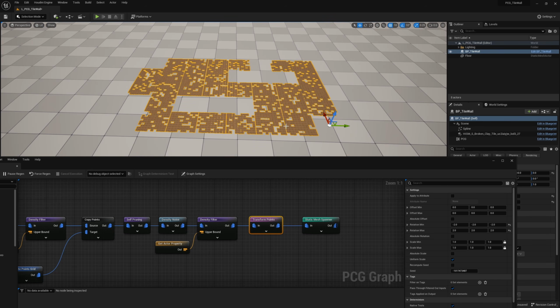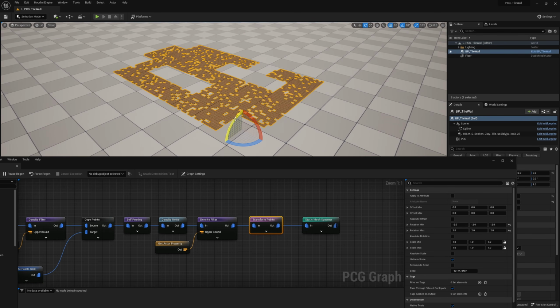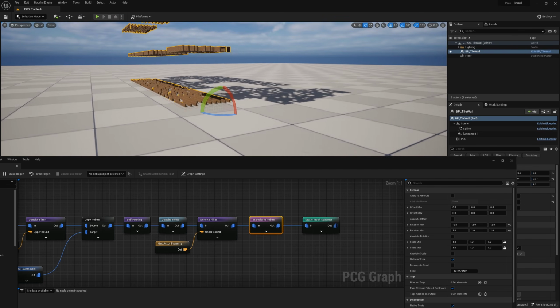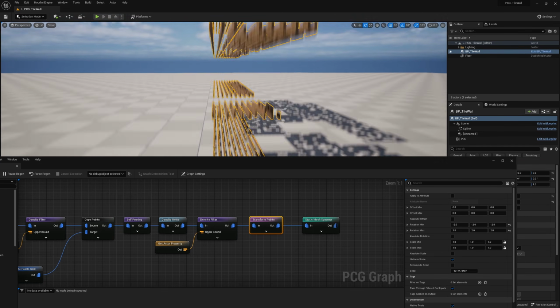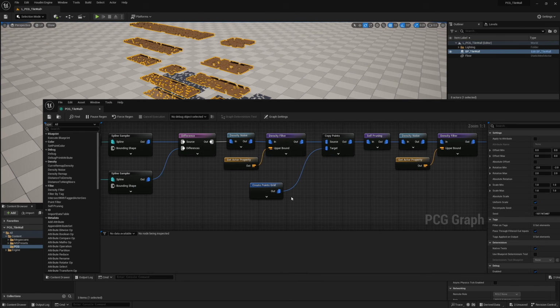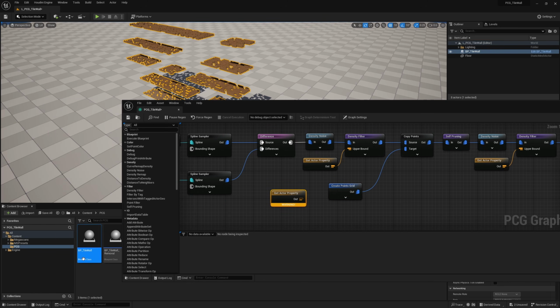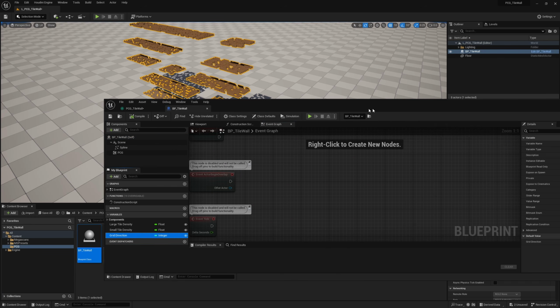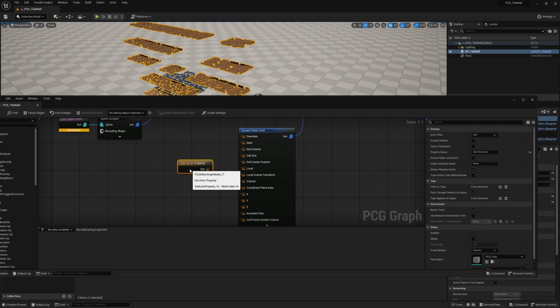Now, we're almost done with this, but you might notice a problem when you go and take this and rotate it. And that is now, because we've copied this grid, it works with the floor, but it doesn't work for the wall. And we can fix this pretty easily with the last variable we created, but we didn't use yet. And that's for this create points grid. So we're going to get another active property. And again, we're going to copy the variable name, this grid direction, and we're going to plug this into our property name. And in the create points grid, what we're going to do is coordinate plane axes.